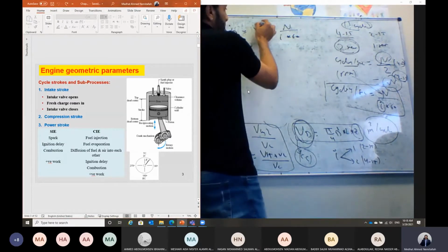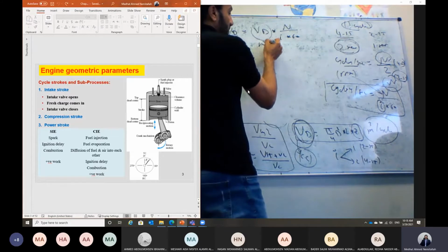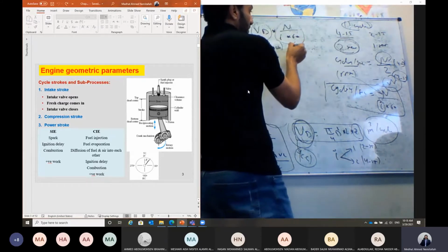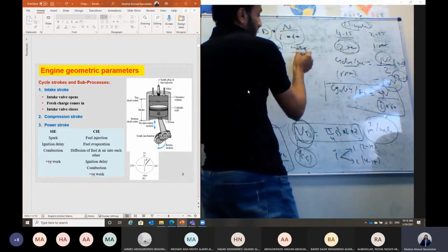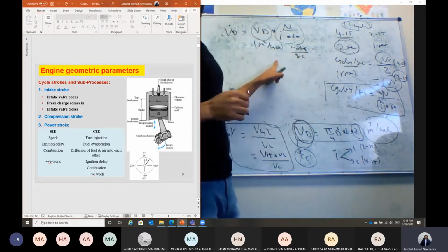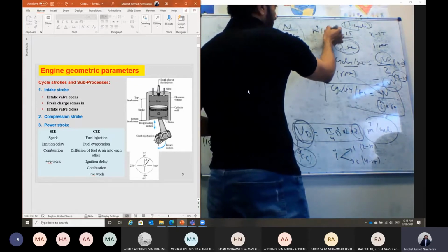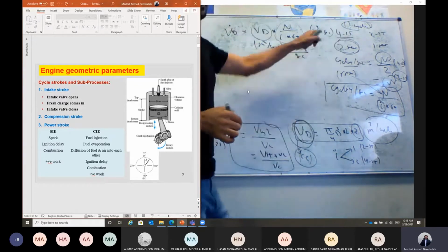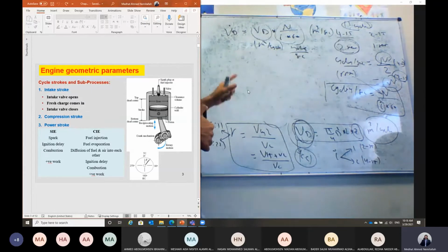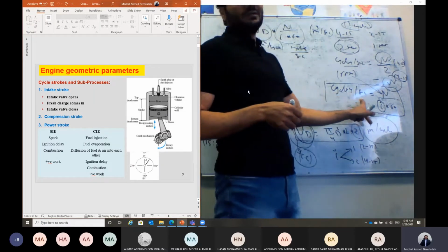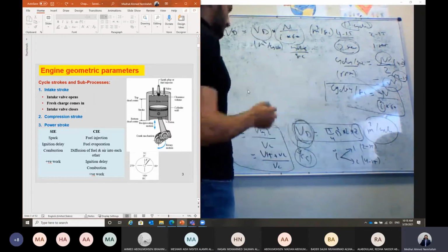This is the volumetric flow rate. This is meter cube per cycle, and this is the number of cycles per second. So meter cube per cycle multiplied by cycle per second. At the end, that should calculate the volumetric flow rate of air into the engine, in meter cube per second. But this is about the number of cycles per second, equal to N over I by 60.